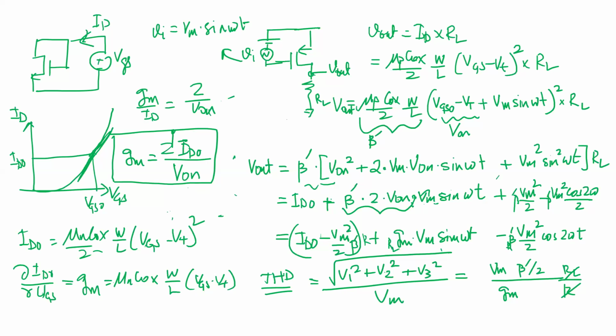Yeah, so this gain is this ID times RL, right? So if you want really high gain, you want a high RL, high output resistance, right? But the problem with that is when you do DC biasing, even a small current, this output will just go. For example, in yesterday's example, we took 200K, and 200K times, let's say 100 microamp, is 20 volts, right?